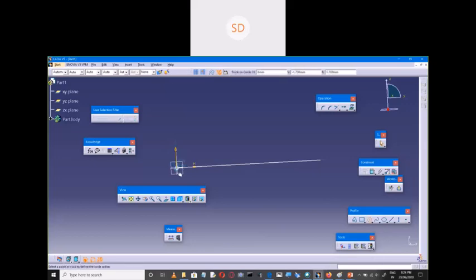Now I have one circle here. Okay, so you can use the tab command to fix the dimensions. Now let us look here. You have drawn this circle at this point. Now actually you need a circle at the midpoint here at a distance of 50, or at the end point. One thing is that you can directly select this one, delete it, and draw once again the required diameter circle here. Okay, right. This is one thing.